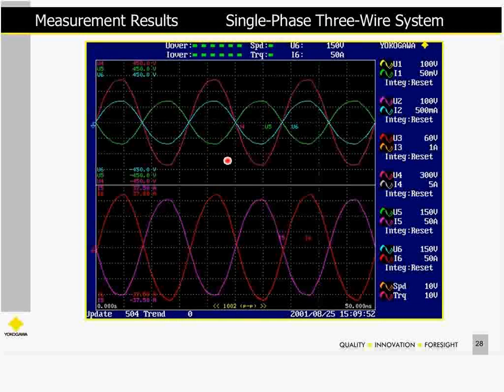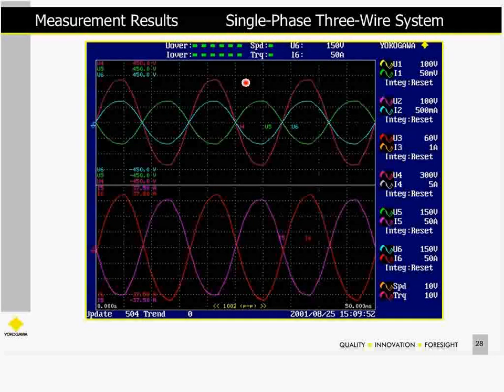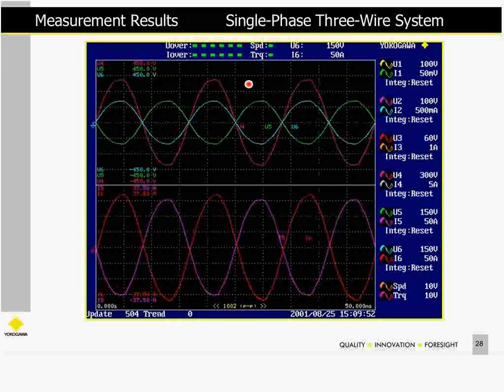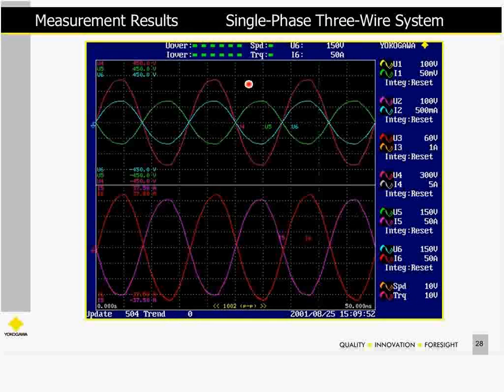Actually, what this device was, was an electric dryer. So part of the circuit was a resistive heating load. The other part of the circuit had a resistive heating load as well as the motor, which was part of the inductive load, which caused that lower power factor. So that's why you have to monitor both lines on a split-phase system unless you know exactly what's inside that device.